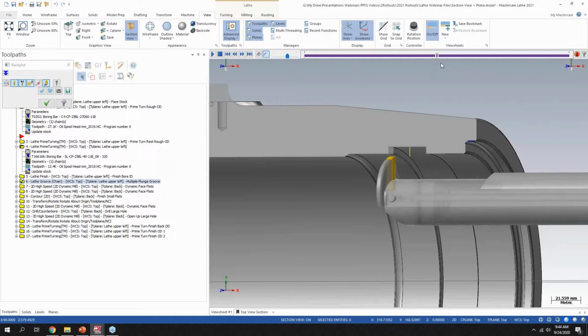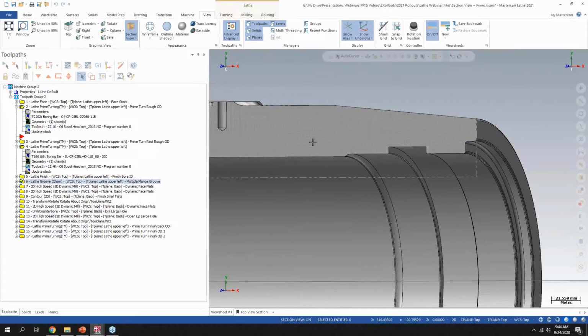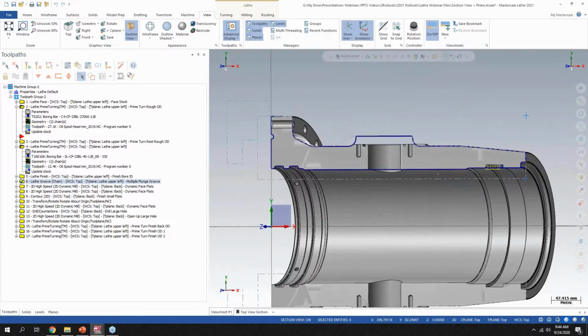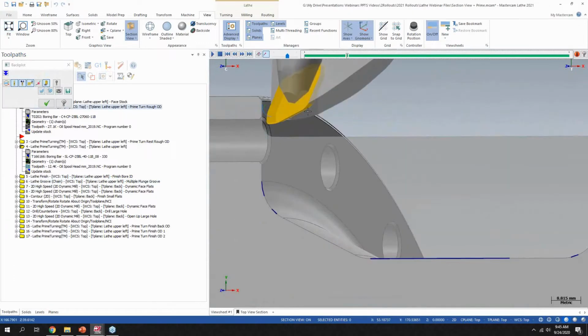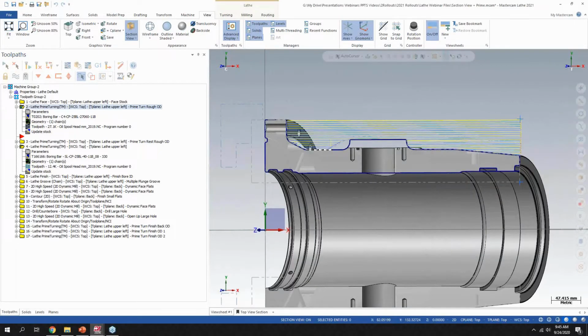And they're mainly designed around cutting away from the chuck. So this particular tool has an insert here where it'll cut off the backside. And my biggest recommendation here is that first you need to know if your parts are a good fit for it and that your equipment can handle it.